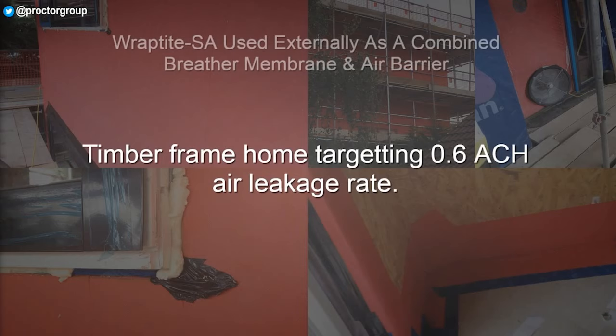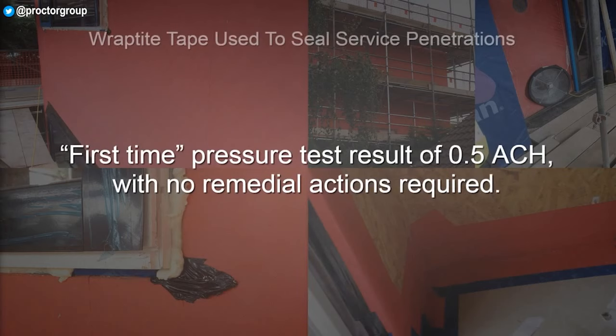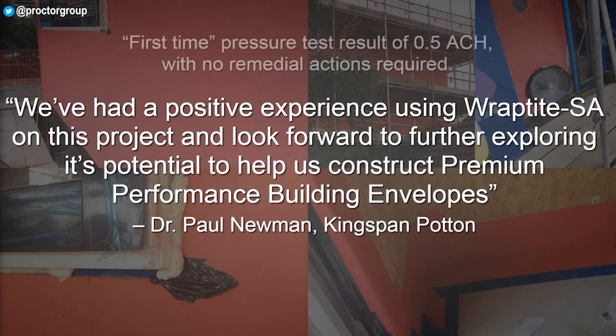Raptite was used externally as a combined breather membrane and air barrier. Alongside that, the Raptite tape, which is a very similar product, was used to seal surface penetrations, window frames, etc. This achieved and is consistently achieving 0.5 air changes per hour with no remedial actions required. You can see Dr. Paul Newman was very happy with the result after quoting, "We had a positive experience using Raptite on this project and look forward to further exploring its potential to help us construct premium performance building envelopes."